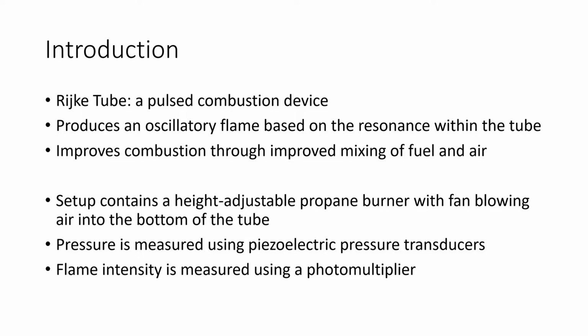Within the Rijke tube, the pressure will be measured using 3 piezoelectric pressure transducers attached through the walls, and the intensity of the flame will be measured using a photomultiplier aligned with a glass panel in the side of the tube.